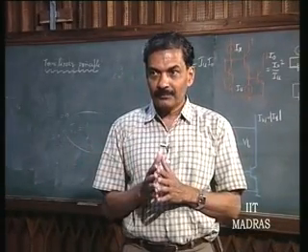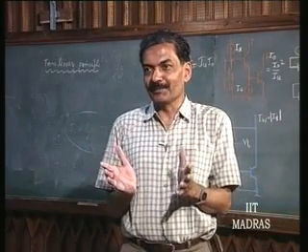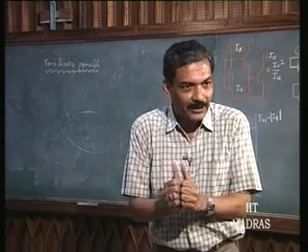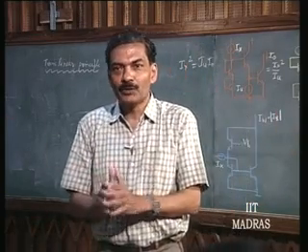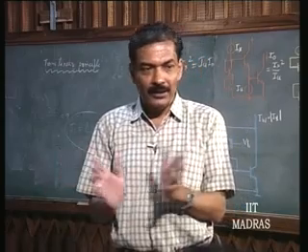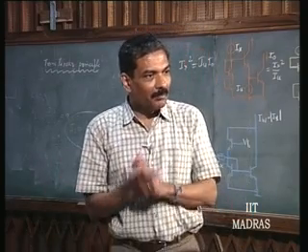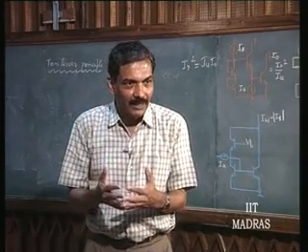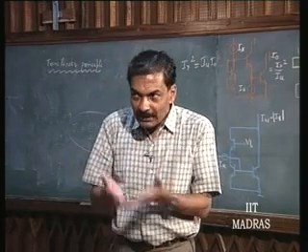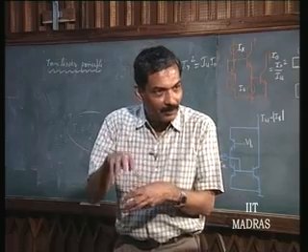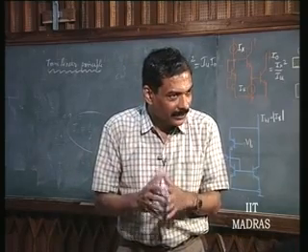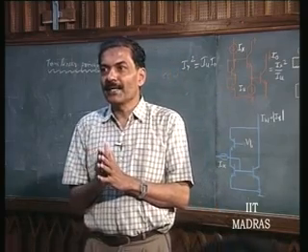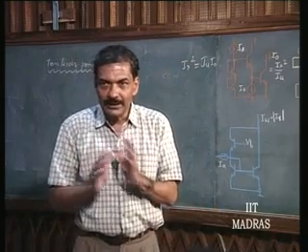But the FETs are a problem. In FETs, there is no such relationship. Exponential is basically data compression. An exponential relationship simply means data compression, squaring has nothing to do with it. That is why the bipolar device is a more popular device signal processing wise than the FET. Even in the FET you are looking for the subthreshold region of operation where the relationship is exponential. So, people are trying to use FETs in the subthreshold region where the relationship is exponential.